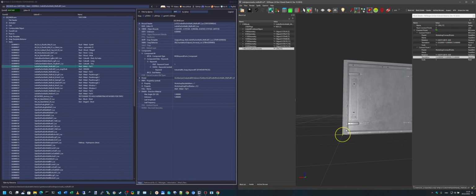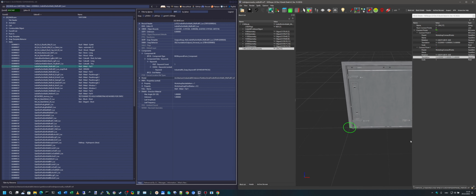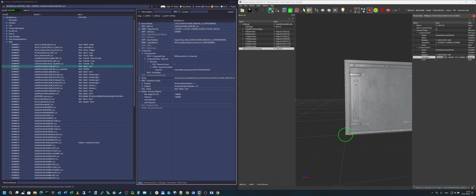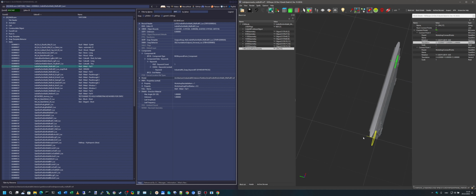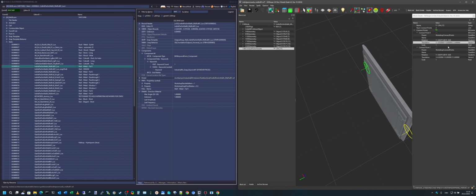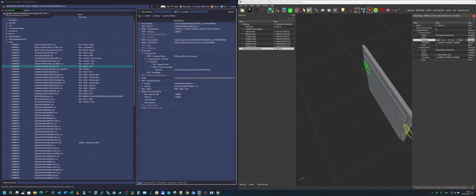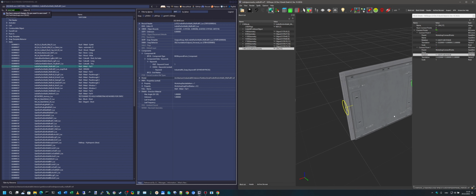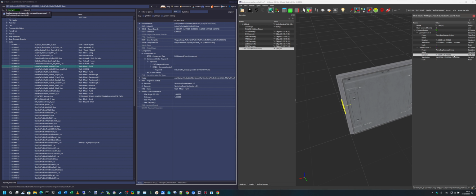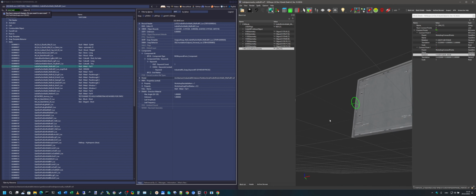Then you have to check it visually. It's 4.02 or something like that. And for visualization, you can put it at some height that you like, the middle of the object, for example. Note that these are pointing the same direction, so this would not snap correctly. You want to rotate them by 90 degrees, and this one, you can try 90, for example. No, it's looking inside the object, so try the opposite, negative 90. Okay, so this looks okay now.